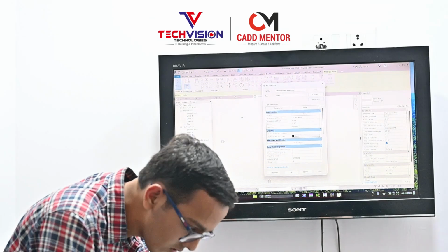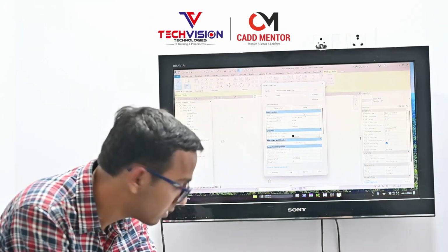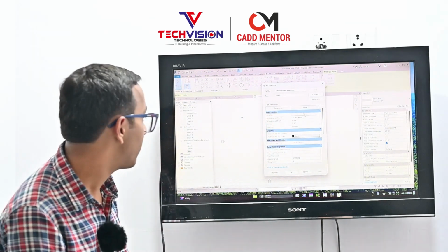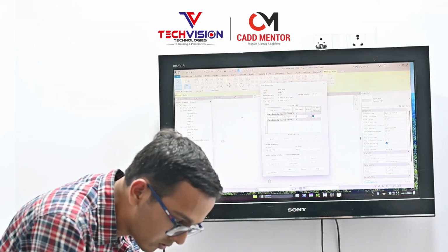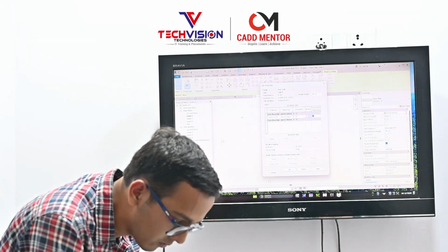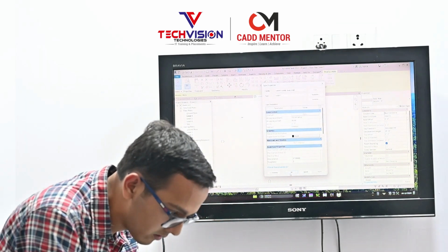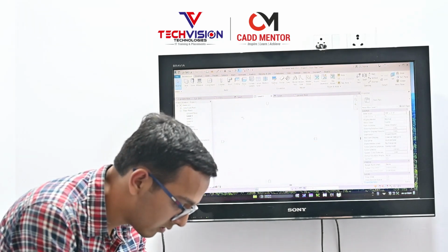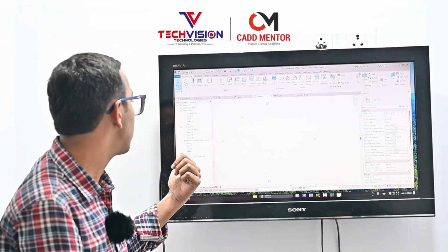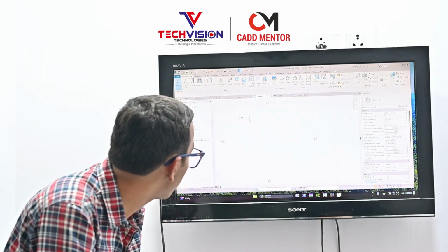And you could see this edit option, structure the construction. Below the construction you could click on this edit option, and then the thickness which we want to give this, 9 inches. So okay, we should click on OK, and then press OK. Then you could see the wall is now a 9 inches wall. It is formed as a 9 inches wall.